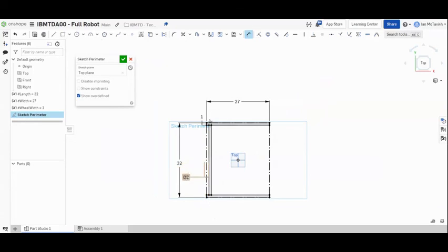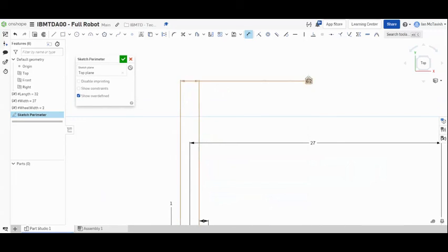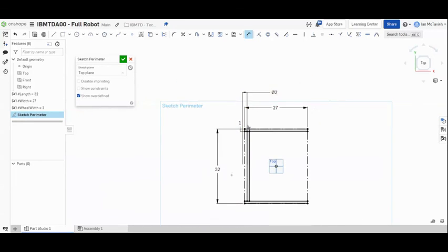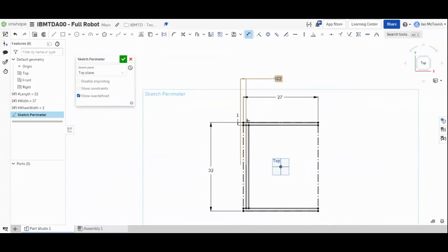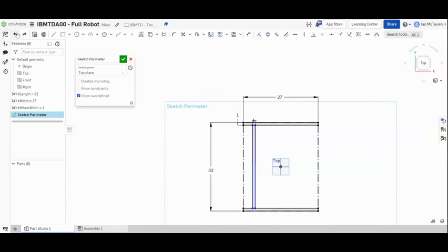So now I have a 2-inch space between those two lines. It's a little hard to see, but if I zoom in, you can see there's little arrows indicating between these two lines, it is 2 inches. I'm just going to undo that and do that again. Okay, so here's my dimension tool. I'm going to click that line and move my mouse, type the number 2. There we go. Turn off the dimension tool.